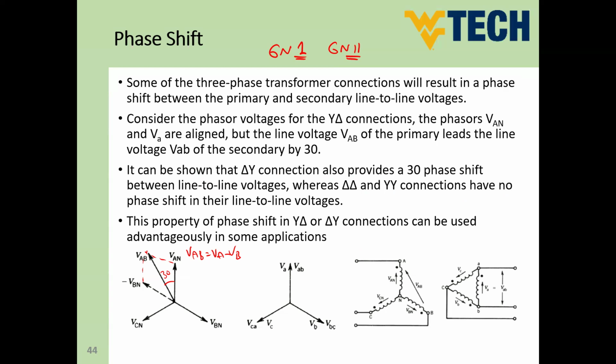By the way, guys, sometimes this makes a lot of problems. Why? Because in our network, if you have any kind of disconnection due to maintenance, when you return the connection back, you have to be sure that the cable that will be connected is going to be in phase with the supply.